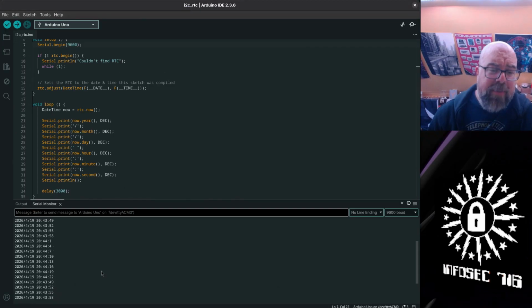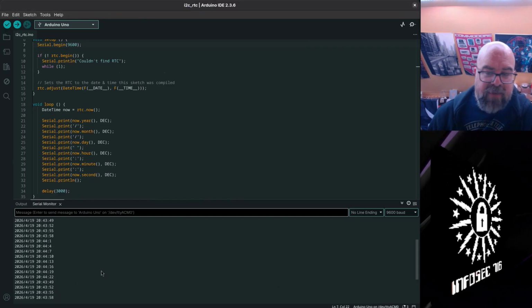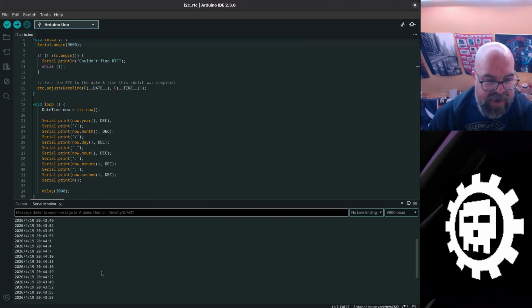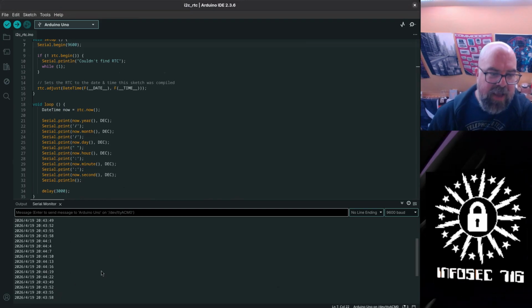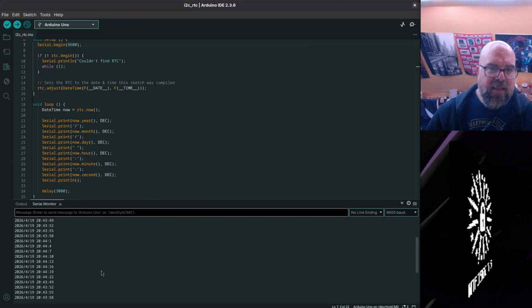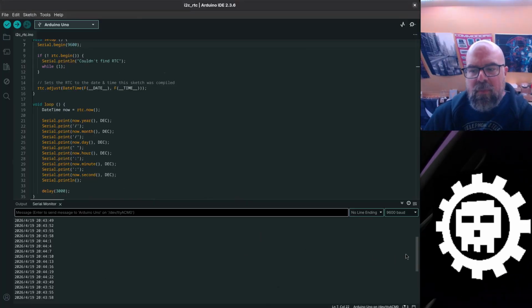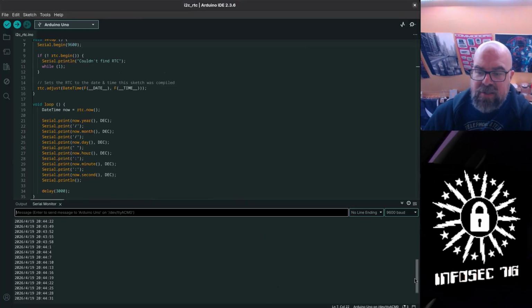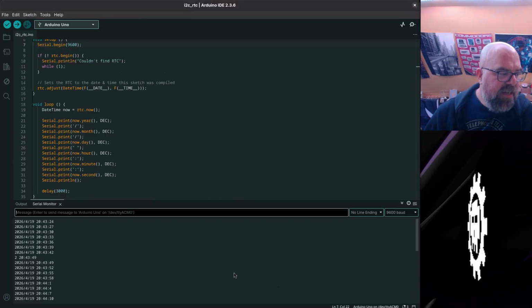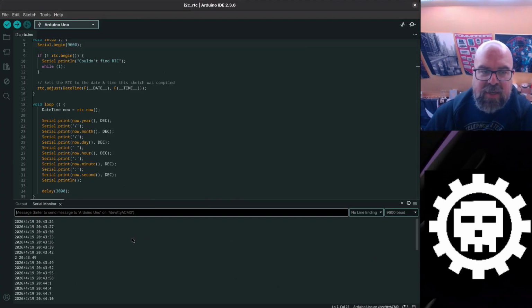That's why that coin battery is so helpful, because if I put a coin battery into this RTC unit, then if I unplug it, unpower it, the clock will continue to advance. And then when I plug it back in, it will have the right value in it, right? It won't need this code to be recompiled and pushed in there again. All right, so that's what the RTC does. It's a hardware device that stores the date and time. I seed it initially, and then I'm able to count from that point and stay precise.